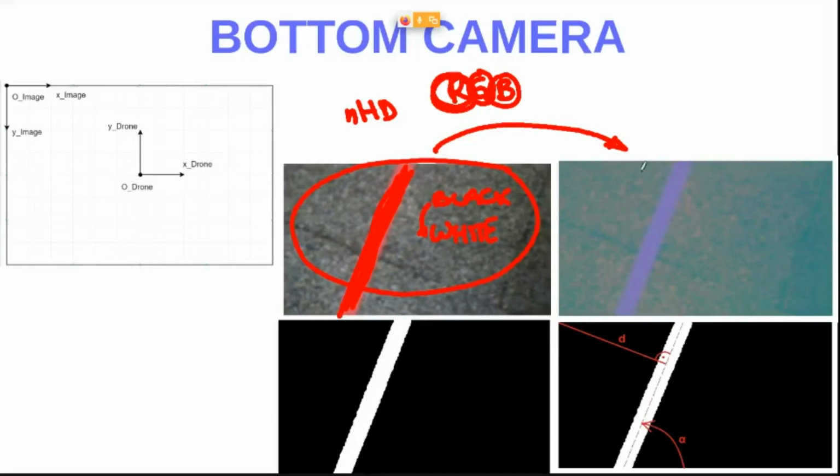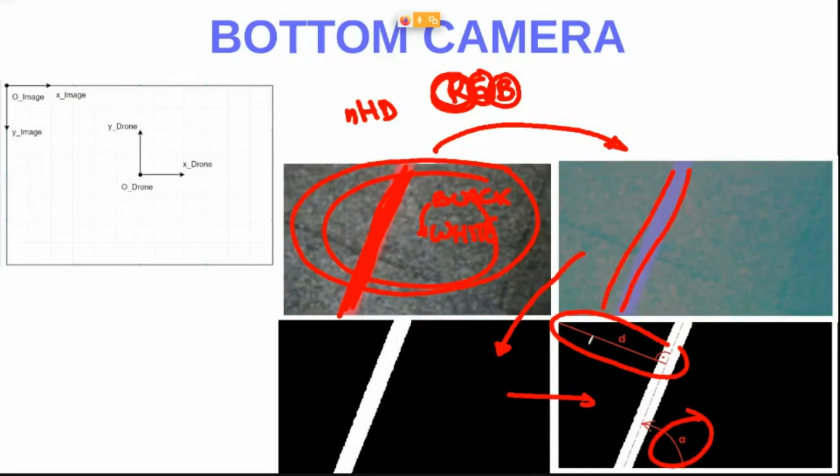I'm going to show you in a session what to do with this image in order to tell the computer that there is a clear line in here, okay? Then we will linearize this image. There are no tricks in here. You can go from this image to this clear image, and here you can see clearly the perfect red tape on the floor, okay? But that's not the end of the image processing, because we need to get the distance and the angle. You remember from the preceding slide, the distance and the angle, because the path tracking algorithm needs these two measures, this in millimeters or meters, depending on the units we use, and this angle in degrees or radians, okay?